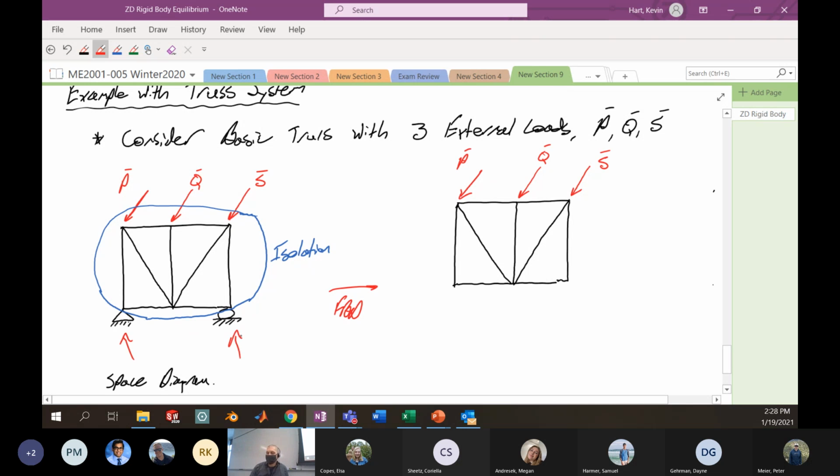When you're looking at engineering problems and thinking about how you want to represent with a drawing things that are actually happening, you need to use some shorthand symbols that represent the actual world. Let me explain what I mean. These symbols here are very specific. The triangle and the circle in 2D stand for a very specific set of reaction forces that I'm hoping to represent with this particular picture. In this particular situation, this down here is a pin.